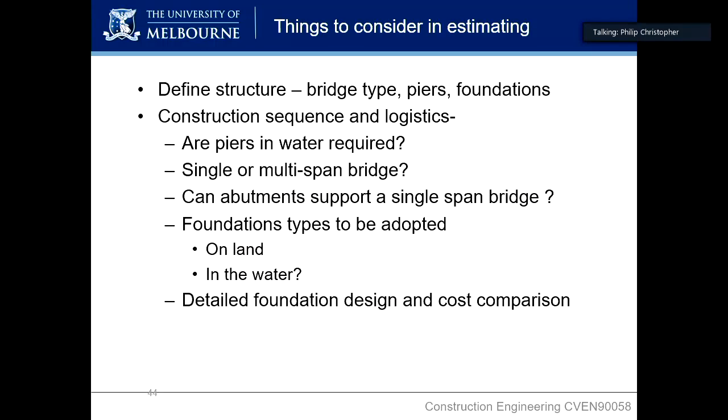But anyway, so things to consider when doing these estimations of piles, bored piles, CFA piles, or your precast piles is, what are you doing them for? You're doing them for the piers of your bridge that are supporting your Super T. So that's what role these foundations are playing here. What sequence and what are the logistics? This bridge is not a top-down or anything, so your sequence will be your piles, your pile pads, your piers, your crosshead, and then your Super T's on top. Okay. Are you doing a single span or multi-span bridge? I don't know. You'll find out after your workshop for sure.